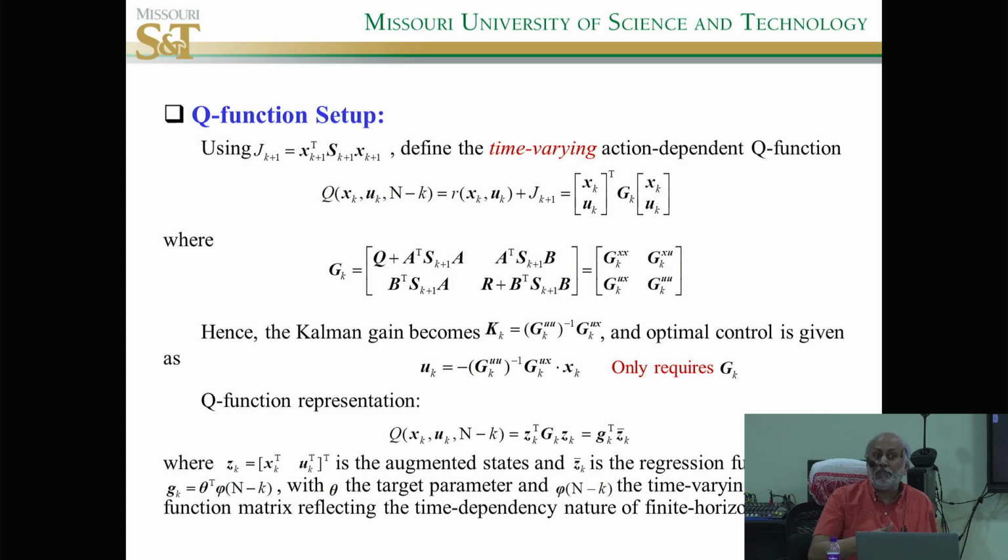This is always what we are after. And here the kk is optimal. This is an optimal gain. When you say optimal, that means it minimizes the cost function. So you use the cost function as a comparison. If you want to compare two controllers, you define a cost function and you see which controller gives you the minimum cost. Okay? Any other questions?